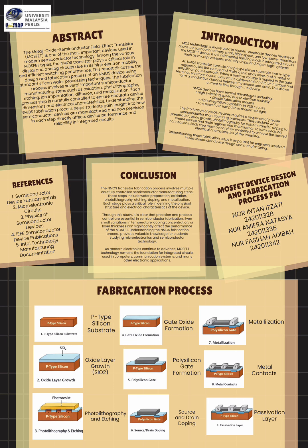MOS technology is widely used in modern electronic devices because it allows the fabrication of small size and low power transistors. The MOSFET is a fundamental building block in integrated circuits such as microprocessors and memory chips. An NMOS transistor consists of a p-type silicon substrate, two n-type regions called the source and drain, and a gate electrode separated by a thin oxide layer.